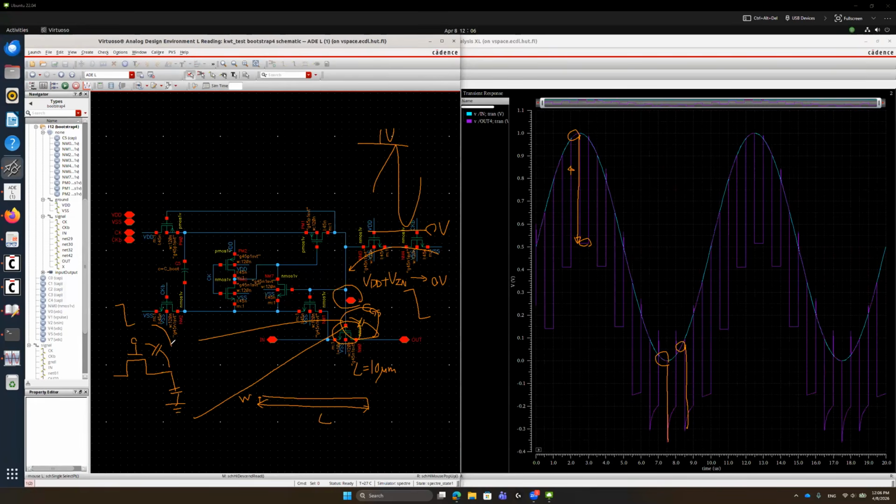So there is a voltage division here and here. So this voltage is instantaneously affected by the negative swing action. We call this kind of phenomenon clock feedthrough. You can study this phenomenon by reading Professor Razavi's textbook, although we have not managed to discuss this phenomenon during our lecture. This is what is happening.